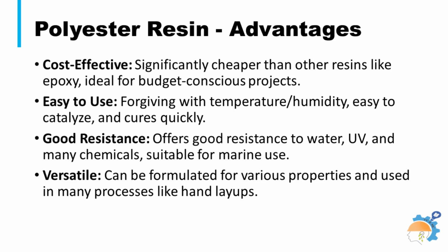Polyester resin's main advantages are its low cost, ease of use, fast curing, and good water and chemical resistance, making it great for general fiberglass, boat building, and molds. This easy-to-handle resin is good for use in fast-curing hand layup, spray-up, filament winding, pultrusion and compression molding.